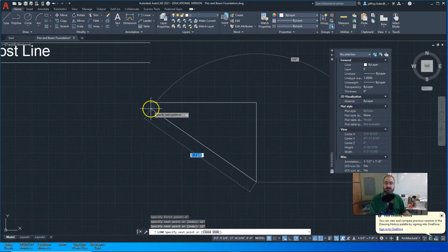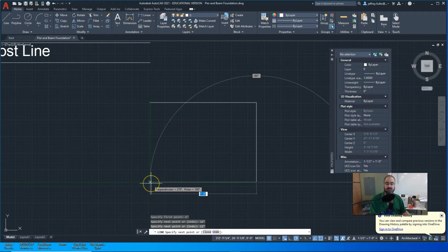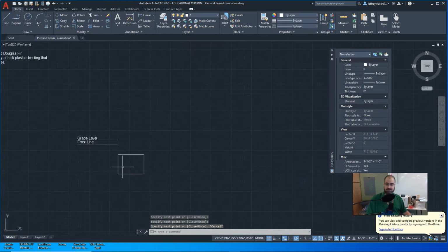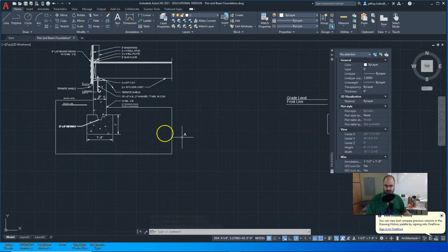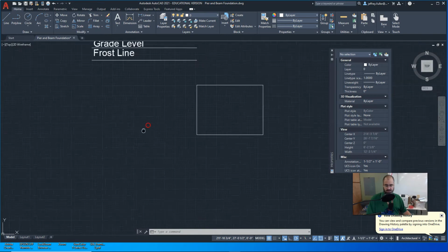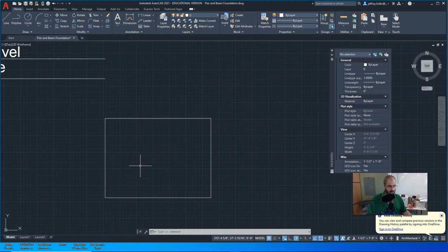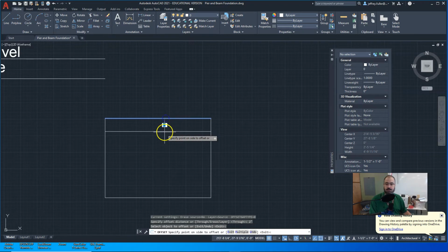I'm going to draw over to the side here to finish it up and just reference that piece of geometry there. There's partially a footing, but I also need what's called a keyway drawn in it right here. Keyway, that really depends. There's no real code that specifies what size that keyway is. I think there are some standards that people go by. One good standard to go by. Now I drew that one a little bit bigger, but we're just going to go by a 2-inch. So I'm going to do an offset, 2-inch. So that offset that line 2 inches.